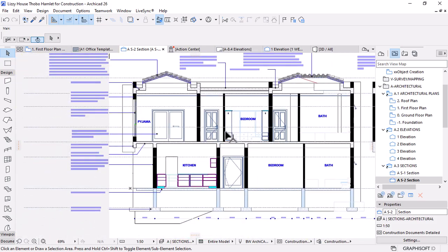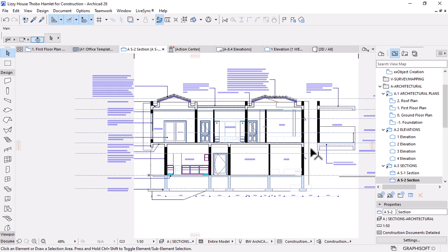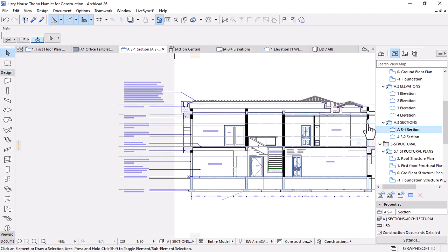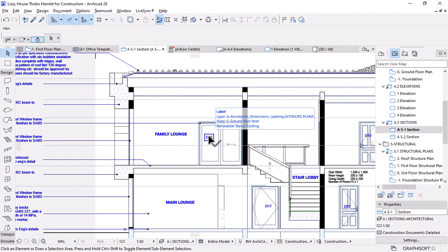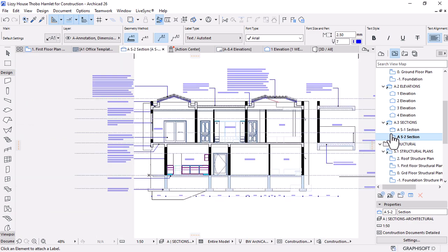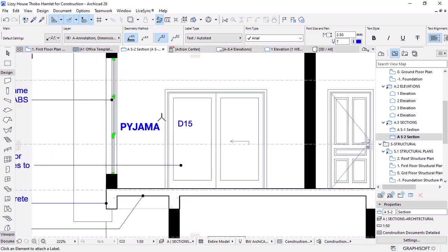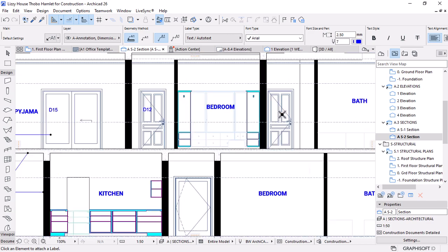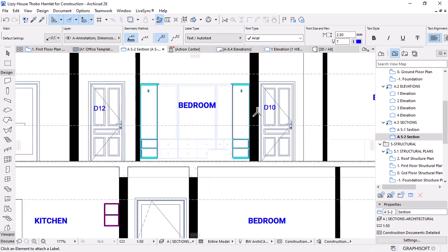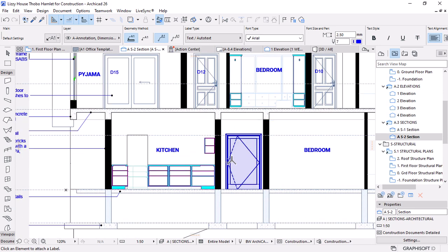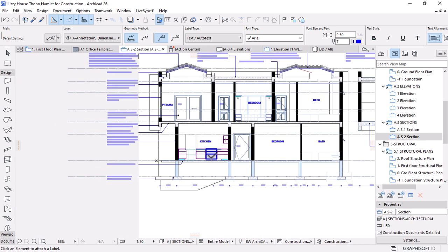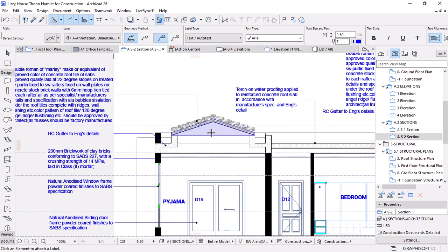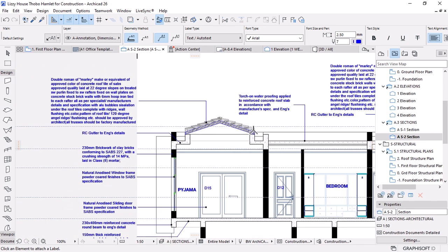One thing that we need to do is to label now the openings. So I would go back to the previous section and pick the label parameter. Go back, start with this one, place the label to the door, to this door as well, and there's another door here. I think they are all placed, they're all covered. I need to give a specification for the roof.